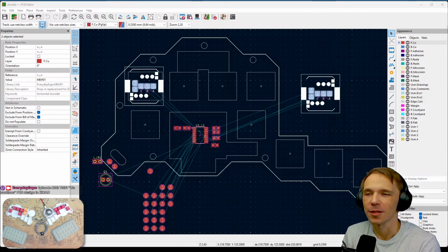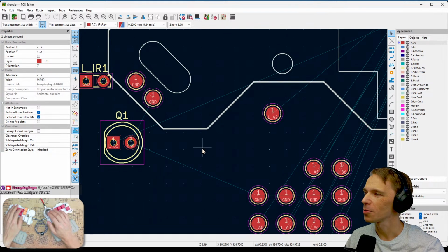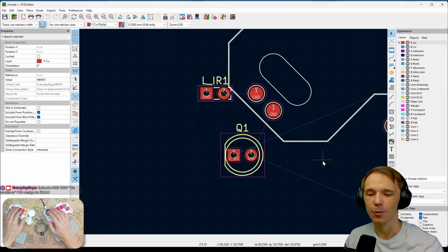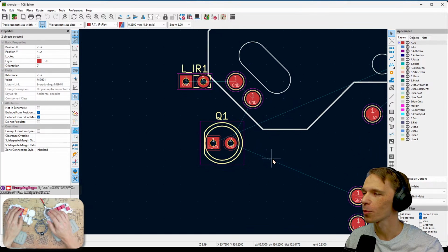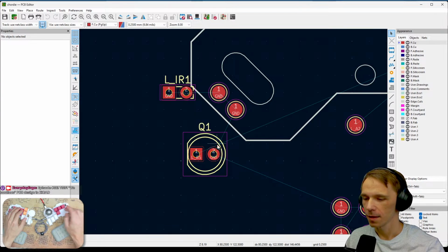I was complaining that I can't remove the text tables from footprints, and that was obviously my mistake. As it turned out later, it's perfectly doable. The issue was that I was treating those footprints the same way I used to do it in EasyEDA. In EasyEDA, the footprint and the text that is attached to it, and everything else, even the nets, is in one properties tab. So if you open a footprint in KiCAD and you press E,